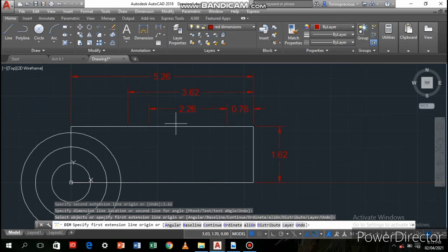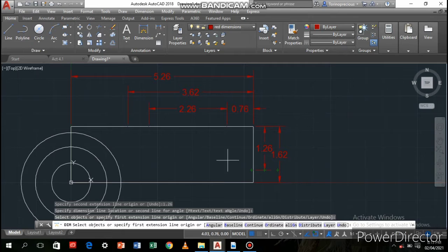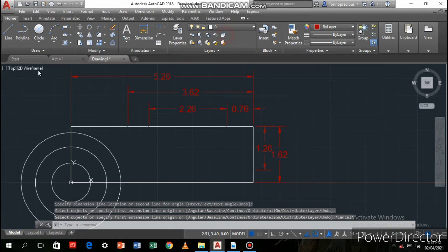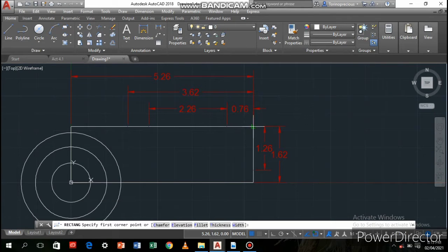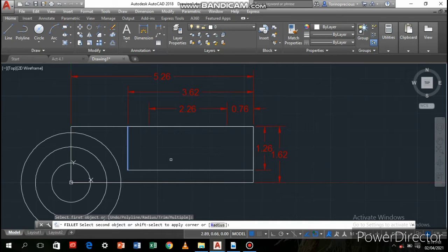By the way, if you are going to create different lines which have baselines and a larger one, it is better to start with the longest one, and then you can continue with the smaller one, since it would be easier for you to create and drag. Next, I will change this corner to be a rounded type with a radius of 0.12.